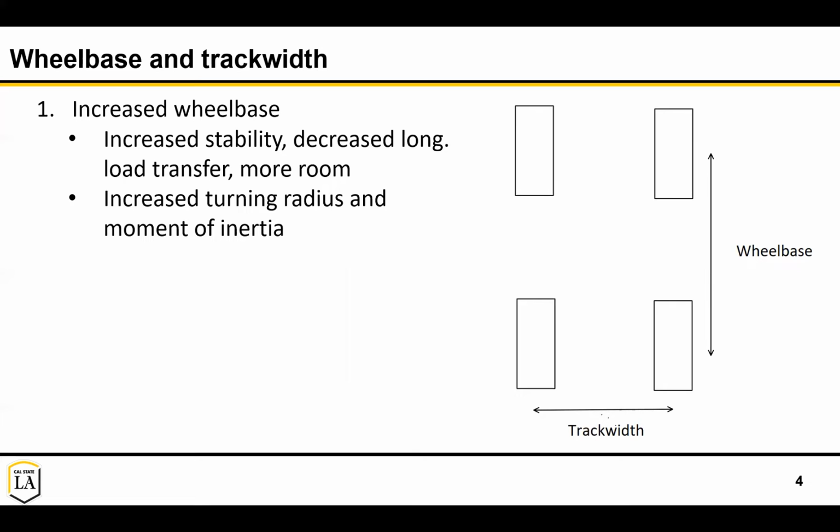You'll find you'll have increased stability, especially at high speeds. You'll have decreased longitudinal load transfer. You're going to have more room for packaging. On the downside, it's going to increase your turning radius, which will reduce some of your agility, and it'll increase your moment of inertia typically.